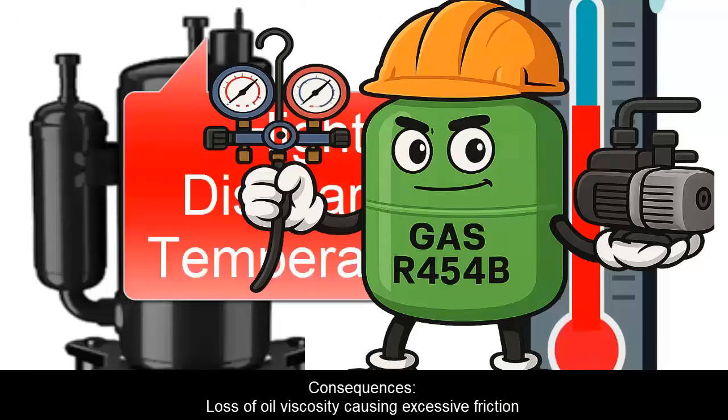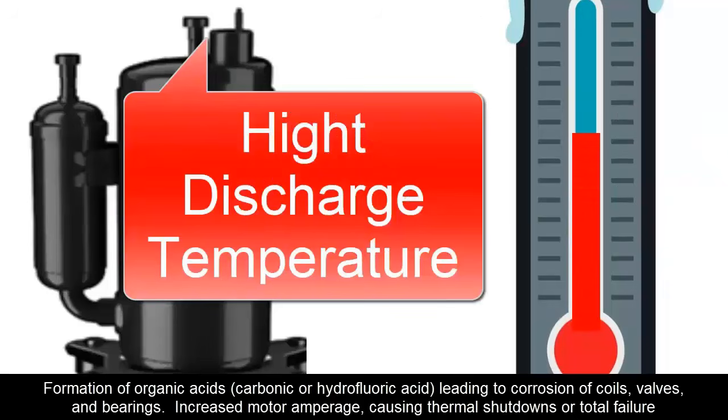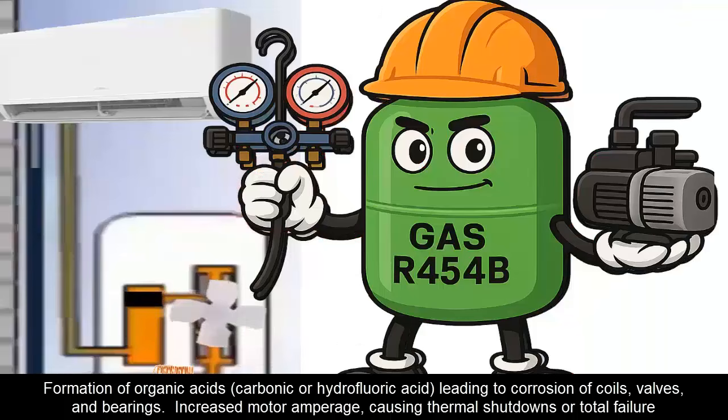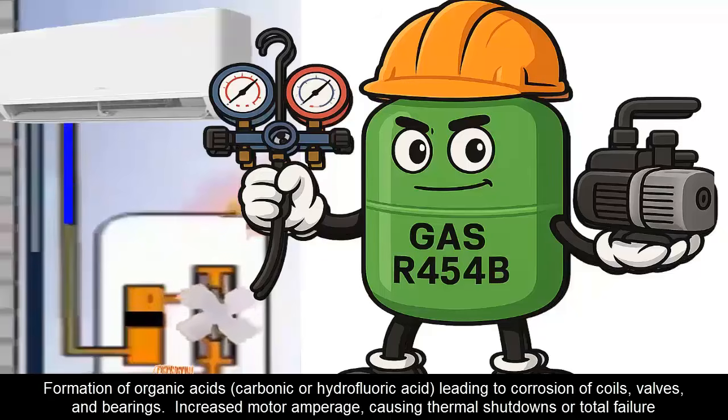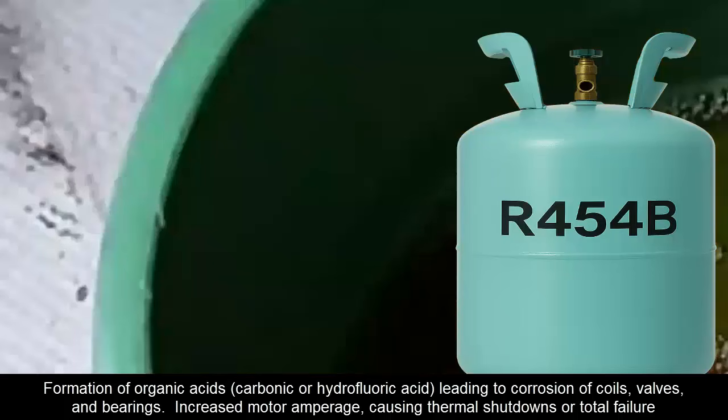Consequences: loss of oil viscosity causing excessive friction, formation of organic acids, carbonic or hydrofluoric acid, leading to corrosion of coils, valves, and bearings. Increased motor amperage, causing thermal shutdowns or total failure.